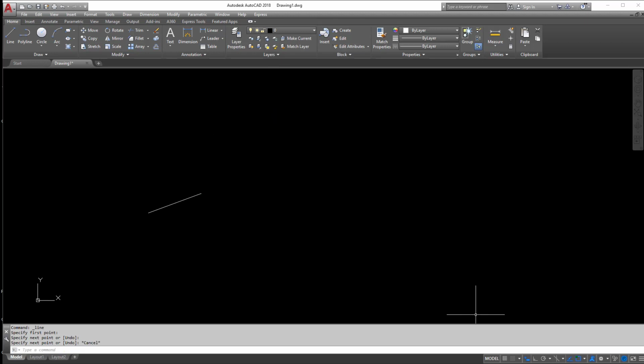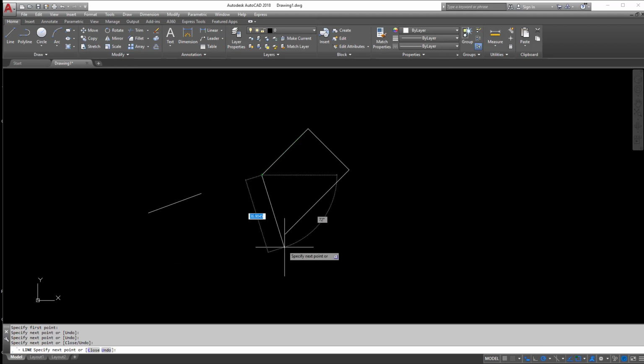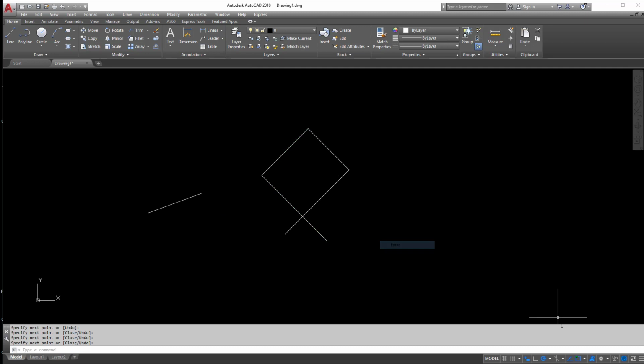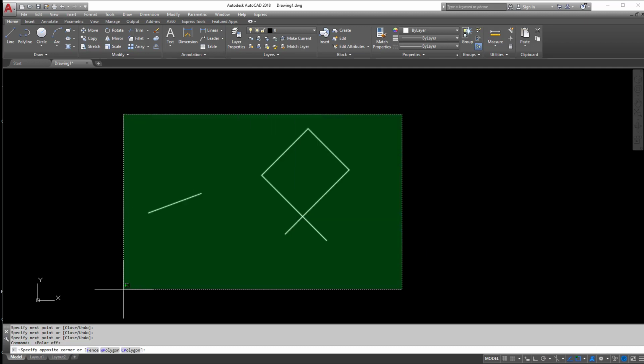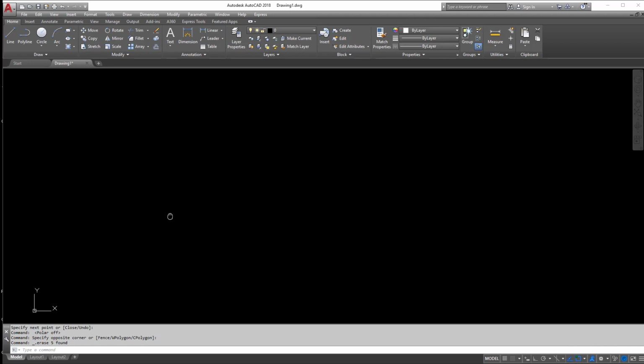Okay, also, if you want to draw a line using polar coordinates, you can always turn this on, and then even with dynamic input on, you'll see it locks itself in every 45 degrees. So that could also help you there. So again, multiple different ways to draw things here. You really just have to pick the one that works best for you.